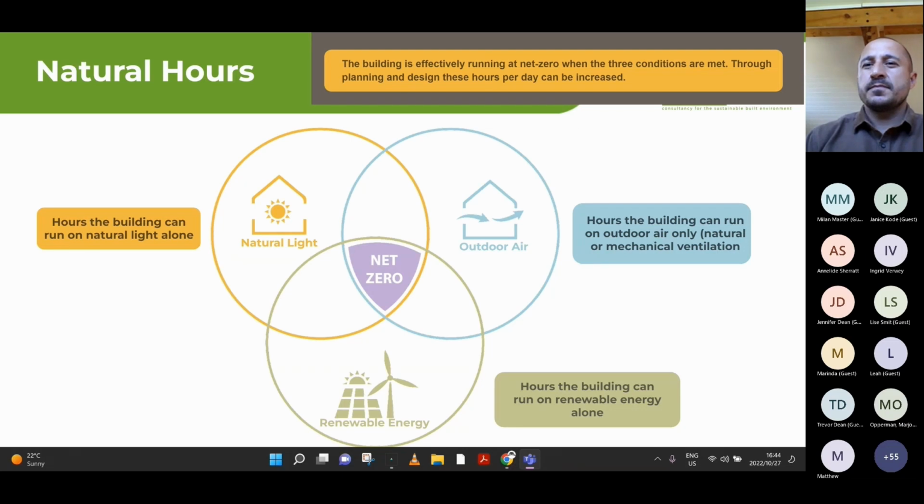Yeah, but those elements are already accounted for, right? By law, you have to have a fresh air system. You will filter, you will do whatever needs to be done. And maybe it's the mechanical engineer coming out, but I prefer mechanical ventilation to opening windows because it's 100% controlled. You know what's coming in, you know what's happening. But that element, it's a legislative requirement. You must provide fresh air. All we're saying is separate it so that if the fresh air is enough, the air conditioning can come off. So as a concept, it's a very simple thing. We're just mimicking natural ventilation.